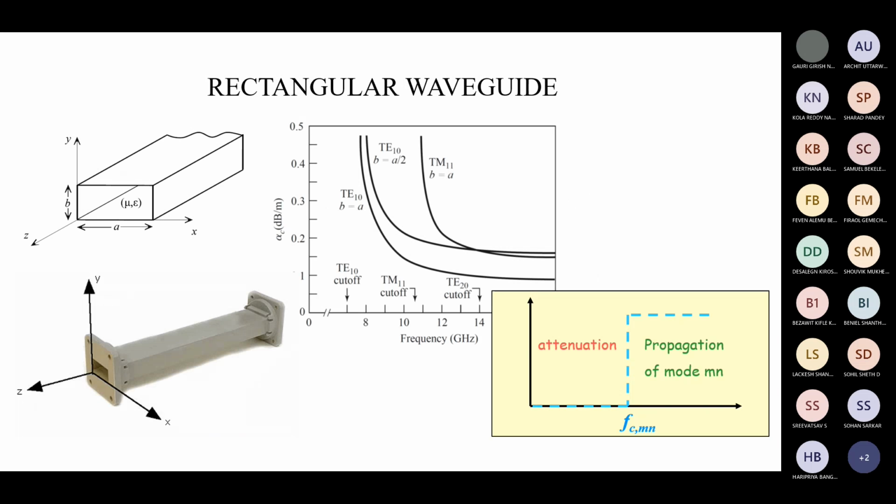And this wave propagation is defined in terms of alpha and beta. It is very much the same as how the wave travels in a medium. Here, in this type of guided structure also, how the wave travels can be defined. And this alpha and beta define 2 regions: one is the attenuation region and the other is the propagation region. Attenuation region means those frequencies won't be allowed for wave propagation. So low frequency signals should not travel through this structure.